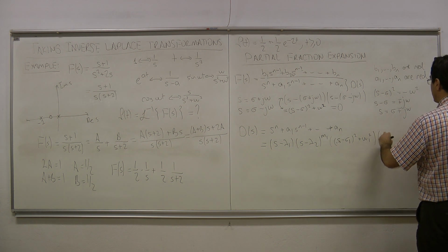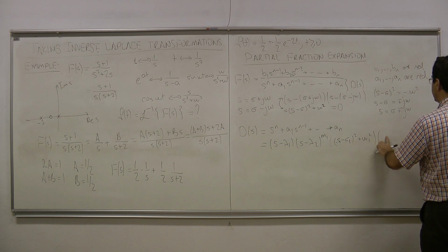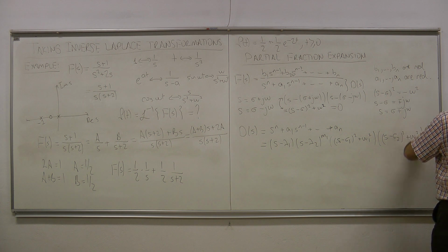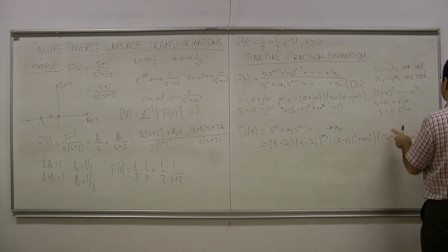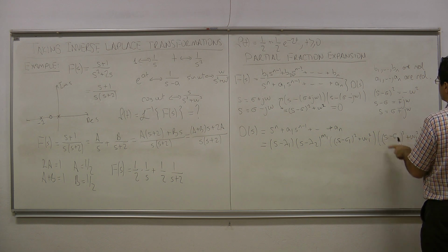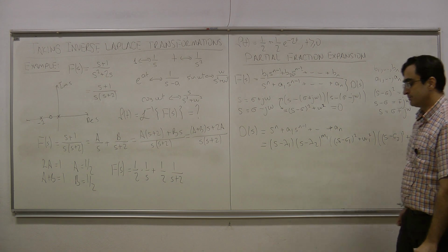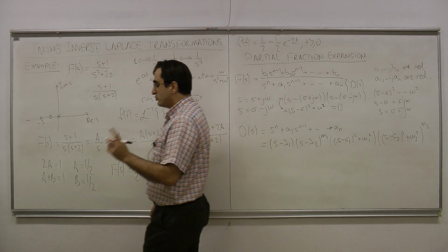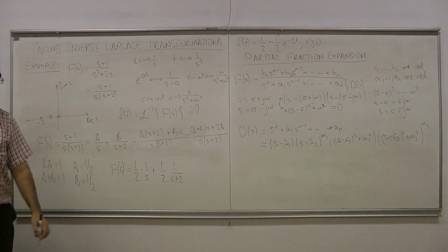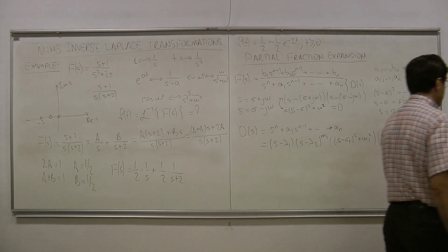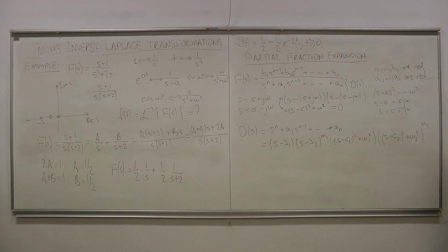And what can happen is that complex poles can have a multiplicity which is larger than 1. Okay? So I will be representing this like this. (s minus sigma 2) squared plus omega 2 squared, and this complex pole term, which represents the complex conjugate poles, might have multiplicity m2. And in that case, at each complex location, I will have m2 poles exactly at the same position. Okay? So in general, our D of s would be looking like such a multiplication.